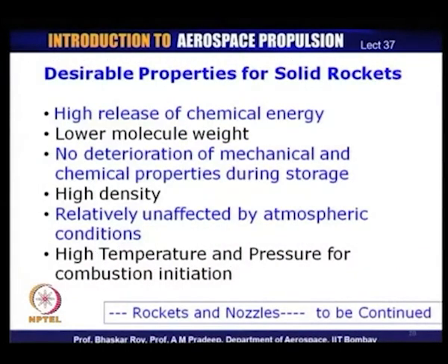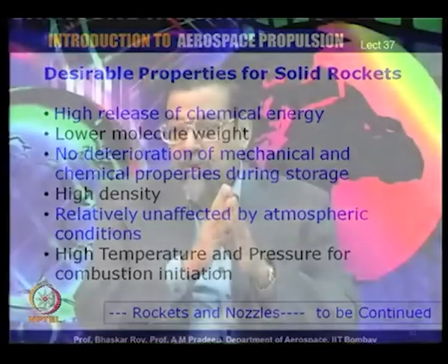The desirable properties of the solid propellants: again, we had desirable properties of the liquid propellants. The desirable properties of the solid propellants are high release of chemical energy, lower molecular weight, and no deterioration of mechanical and chemical properties during storage. Most of the solid propellant rockets are created in specialized factories, and they have to be stored for a long period, during which there should not be any drop in the mechanical or chemical properties, because they need to retain them during their actual operation inside the rocket chamber.